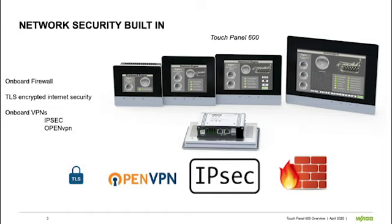The user can also enable the onboard firewall to help against unwanted device access. When the firewall is enabled, it can be set up with a MAC or IP whitelisting that will allow only known devices to communicate with the HMI. In addition, the firewall can be used to enable or disable Ethernet ports and services, helping to limit network access.